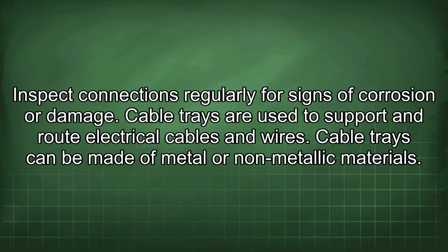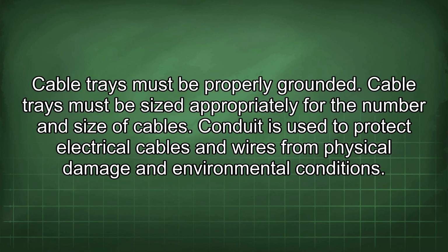Cable trays are used to support and route electrical cables and wires. Cable trays can be made of metal or non-metallic materials. Cable trays must be properly grounded. Cable trays must be sized appropriately for the number and size of cables.